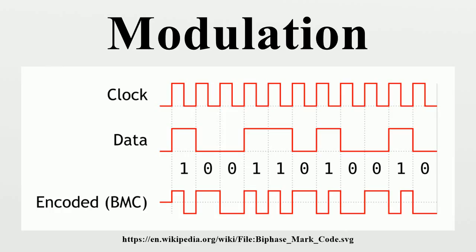In all of the above methods, each of these phases, frequencies or amplitudes is assigned a unique pattern of binary bits. Usually, each phase, frequency or amplitude encodes an equal number of bits. This number of bits comprises the symbol that is represented by the particular phase, frequency or amplitude. If the alphabet consists of N alternative symbols, each symbol represents a message consisting of n bits.